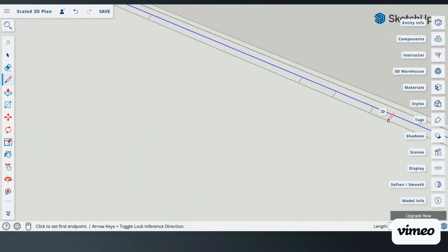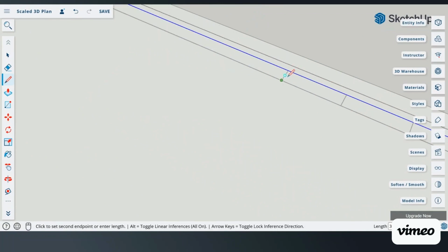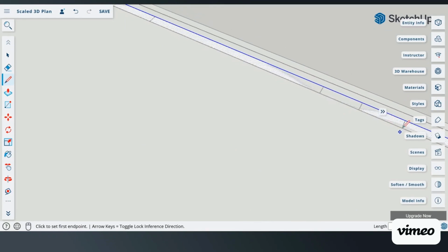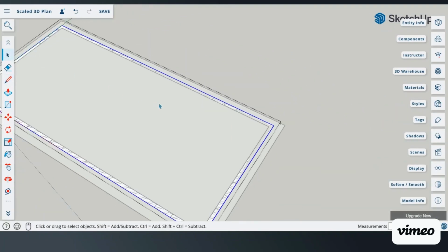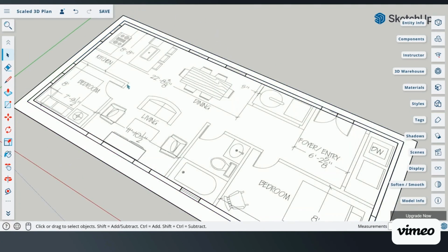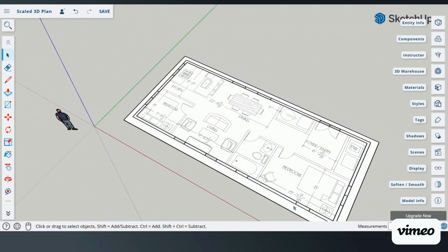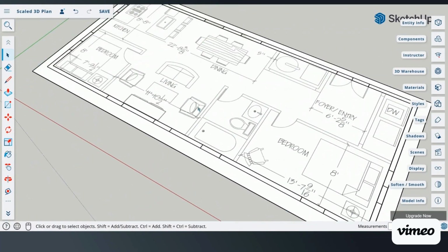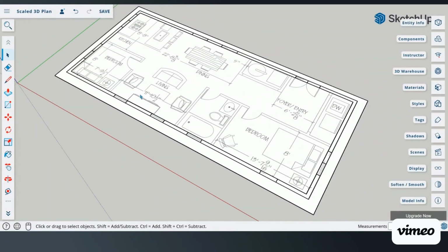And then you will come over to also where your door is and go ahead and draft in the lines that represent the outline of the doors. Once that is completed, now you can click out of your group and all of your windows, your door is attached to the group of the exterior shell.